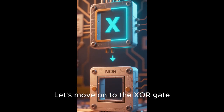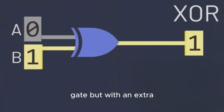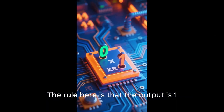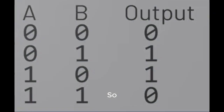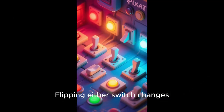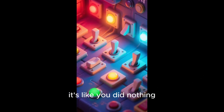Let's move on to the XOR gate, which stands for exclusive OR. Its symbol looks like an OR gate, but with an extra curved line on the input side. The rule here is that the output is 1, or true, only when the inputs are different. So, if one input is 0 and the other is 1, the output is 1. But if both inputs are the same, either both zeros or both 1s, the output is 0. Think of a two-way light switch in a hallway. Flipping either switch changes the light state, but if you flip both at once, it's like you did nothing.